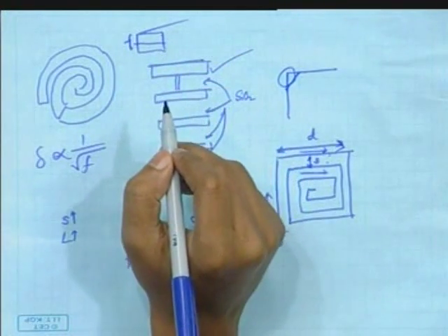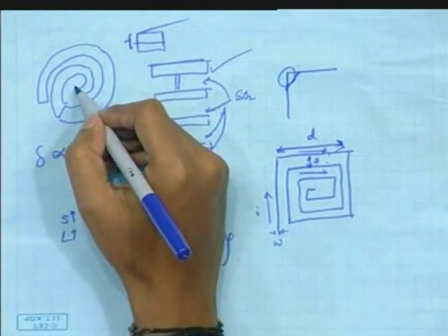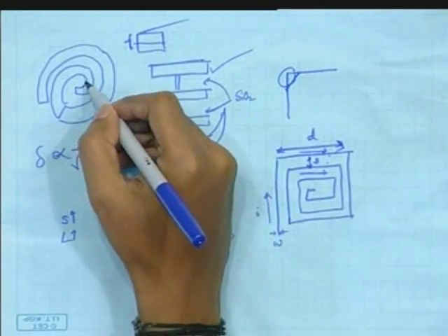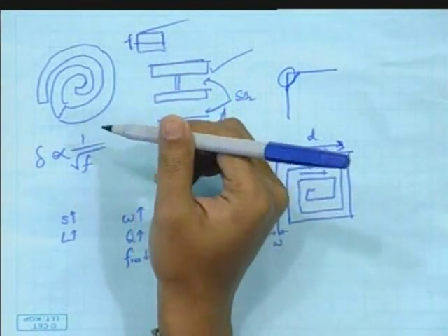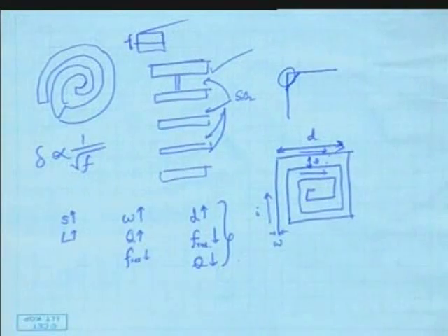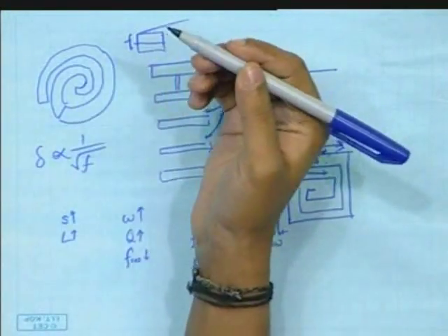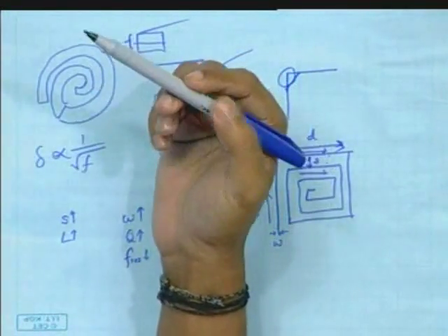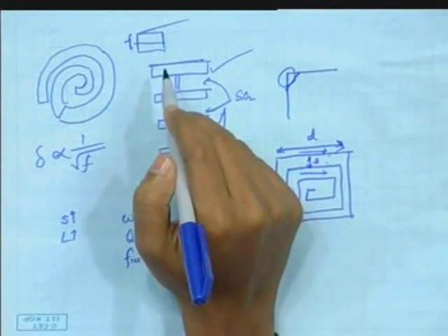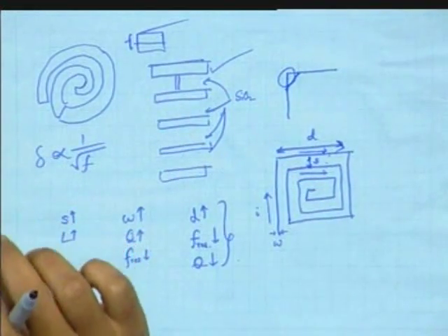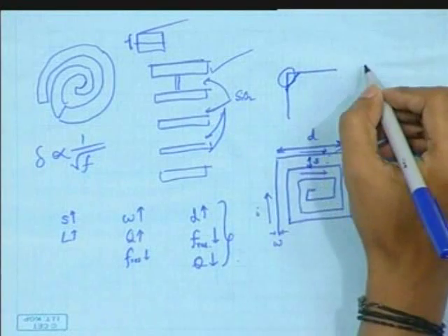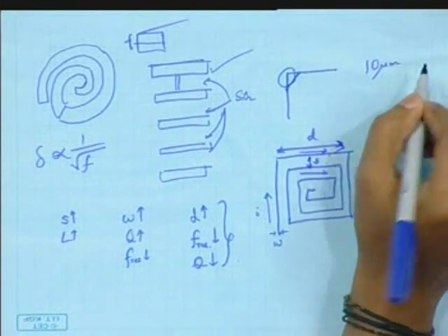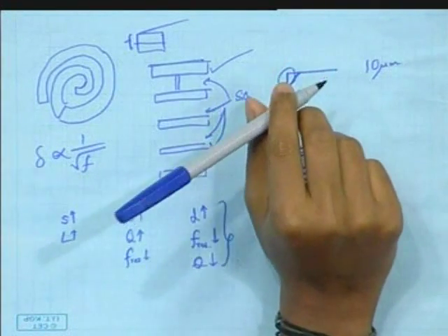So part of the research in modern CMOS processes is to reduce these substrate losses by properly fabricating the metal layers. Even the metal layer at the top is not much distance from the substrate, because CMOS itself is not a very thick process. It's around 10 microns thickness. Now that is enough to ruin your circuit in terms of substrate losses.